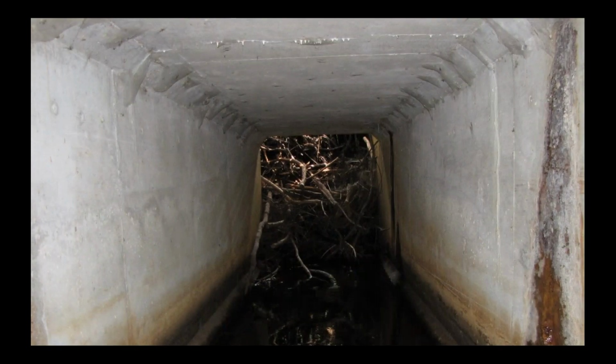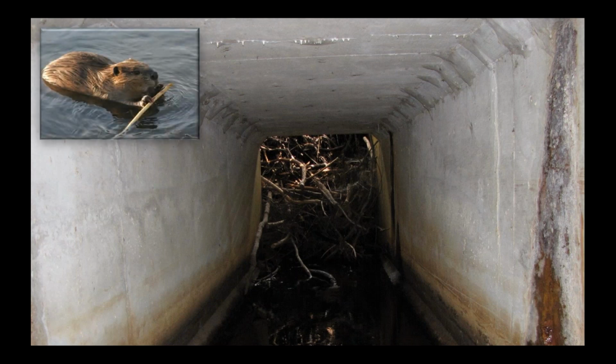This is another unusual condition, and it's really the poster child for why we need to inspect the conduits in dams. Now, this conduit was large enough that it could be inspected by a manned inspection. It was a 5 by 5 foot opening, and we could walk through the conduit. And as we approached the riser structure, this is what we found. And it turned out that the beavers were very busy. They were cutting trees down on the toe of the dam and bringing in the branches one by one, and the entire riser structure here was being filled with woody debris.